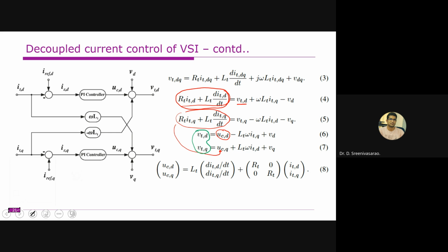All right, so how are we estimating this voltage drop? By using a PI controller. Come to this figure. You have the reference d-axis current here, right? How is this obtained? This reference d-axis current, ID star, is equal to P star divided by VD, right?